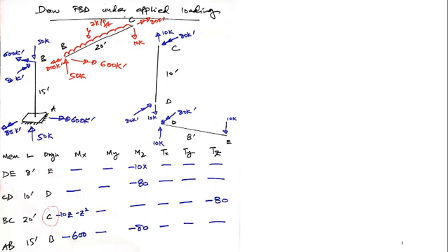Okay, this is my pen. So I have to find all moments here. You should know that this 10 kip would form a clockwise moment, and you should know this distance is Z. This load is in Y, this member is in Z, so the moment would be in MX. The combination is Y, the member is in Z, so moment would be in X.